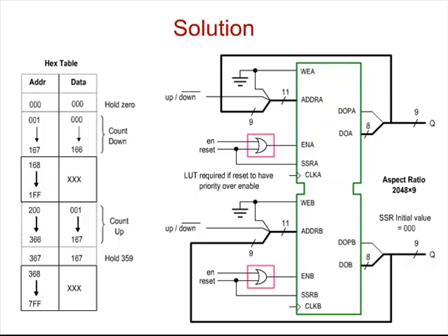Now, the most elegant thing about this construction is that once it's made, it can be used twice. Remember that our original design needed 10 of these counters, but we can make 2 of the counters from one block RAM. That is because the block RAM is dual port and has separate ports. So once a table is used as a ROM, it can be accessed twice. The ROM does not need to be paged if the same contents apply to both ports.